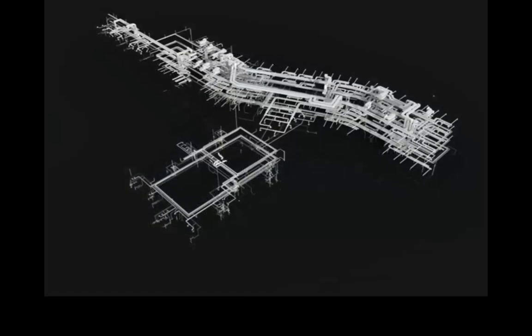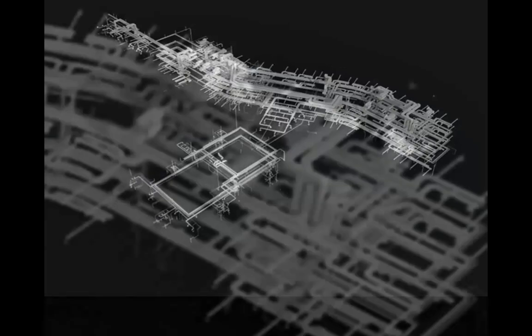That's a bit blurry, I'm afraid, but this is just an extract from the Revit model showing the implication of the mechanical ventilation route. So everything you're seeing on there is ductwork for air. Okay? So the building is then completely full of ductwork. The issue about mechanical ventilation is because you need to move a lot of air about, you need very big ducts to push that air through the building. Sorry, it's a bit blurry.